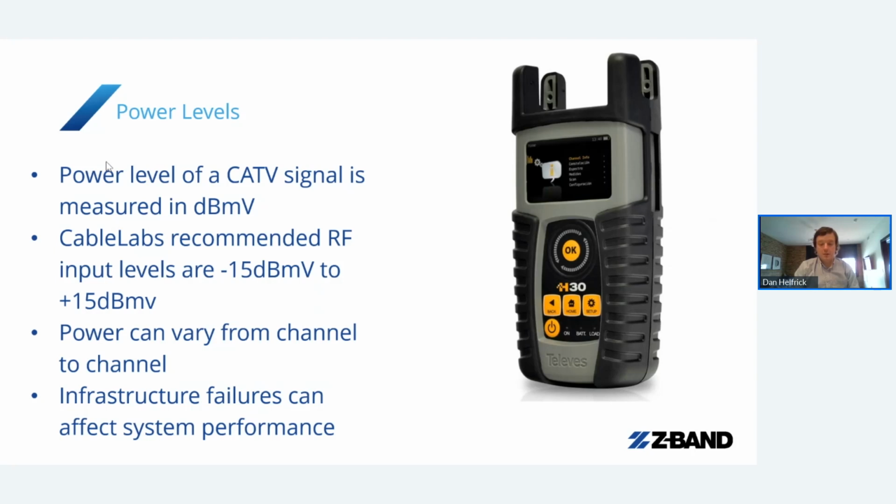Anytime you do a 1x2 split of a coax infrastructure or of an RF infrastructure, you're basically losing about 3.5 dB, but with taps and some other things, these numbers can vary. But if it's just a passive splitter, you're going to lose about 3.5 dB every time you split that signal. And so when we're talking about a range of 0 to 10, you can only really do a couple of splits until we're going to lose that power, right? We're not going to be able to be in the sweet spot for these digital television tuners.